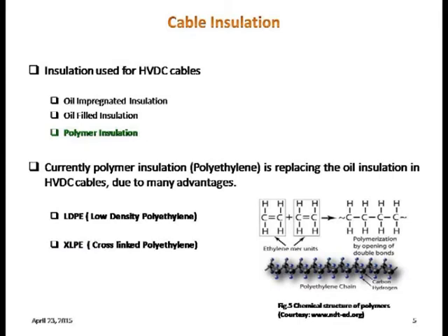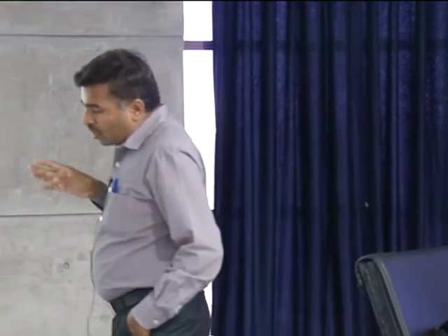Cable, unlike an overhead line suspended in air, where even if breakdown or flashover occurs it can regain its strength and continue to be used, if it fails, you have to replace it. There is no other way. It is because of the failure of the solid insulation. Once it fails, that's all, failure only. So ensuring reliability of cable transmission is very, very important.